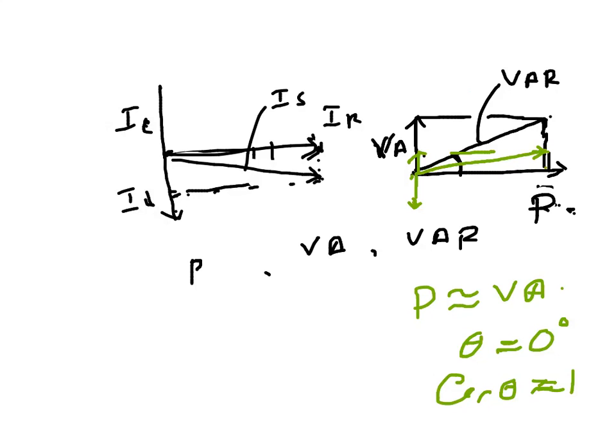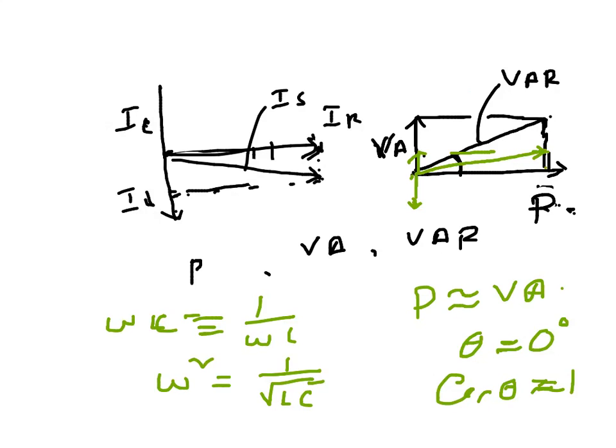It's similar to that RLC circuit as we saw before. If for a moment we forget the capacitance there, just the RL, we have an inductive load, but with the capacitance the total current is decreasing. And also we can notice one thing, that here also resonance is happening when omega C is equal to 1 over omega L, and when that's happening, the resonant frequency is the same as the series resonance circuit. Only difference is, in this case, when the resonance happens,